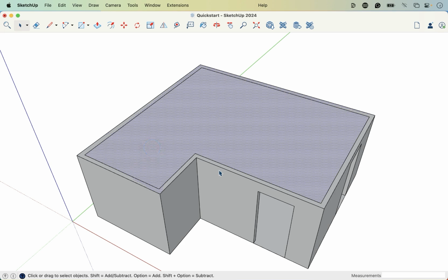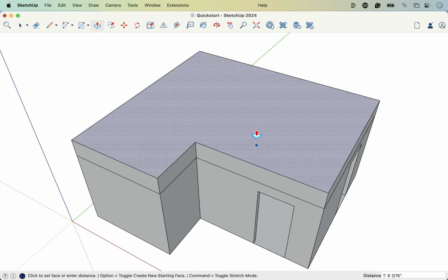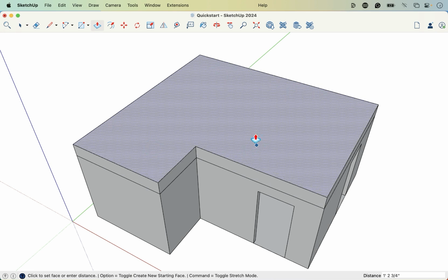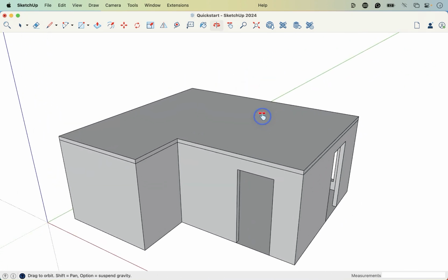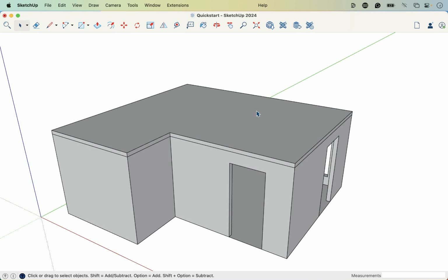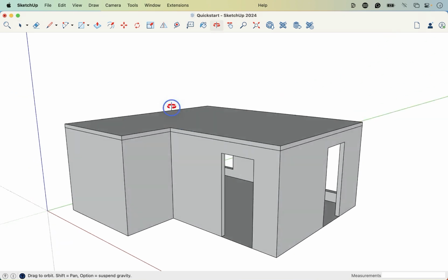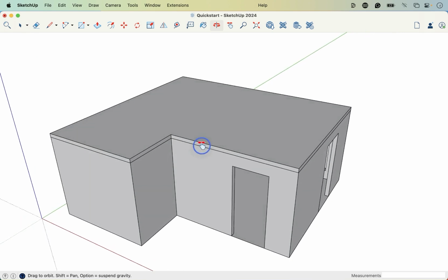So once you have this face here, we can hit P, push-pull, click release, move upwards, and the height of this doesn't really matter. I usually start with 4. Enter. If you are putting 2 stories together, it might want to be something more like 12 inches for the floor above, ceiling below, that thickness there. But I usually just start at 4. Just give it some thickness.